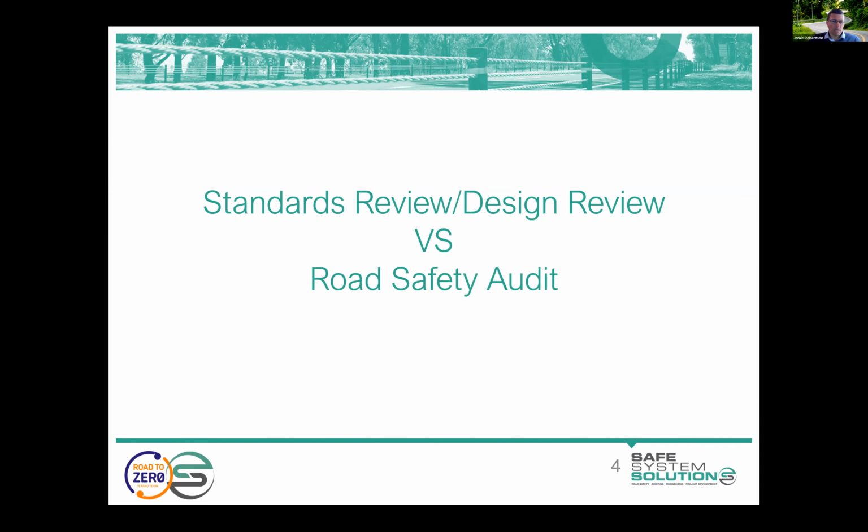A road safety auditor has the luxury of looking at a project with their road safety hat on only. They're not constrained by other considerations of the project, such as cost and environmental impacts and so on. So look, if we're designing something to standards, it has a level of safety, but with any design element, there is a spectrum of acceptable values. There are minimums right up to the desirable level. And it's when we're combining a range of minimum standards that we often do come into trouble.